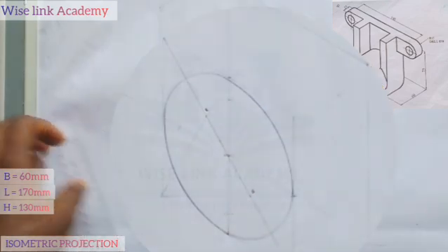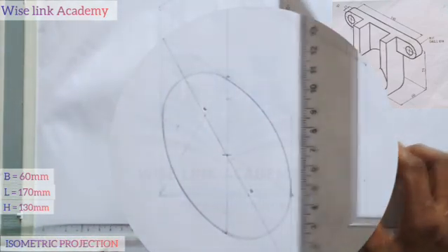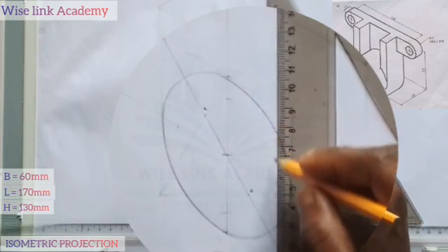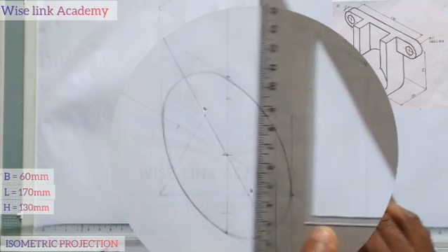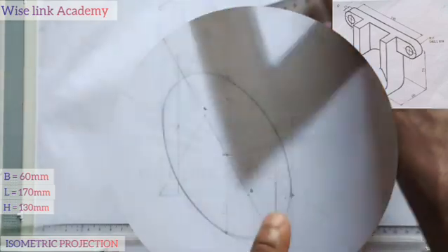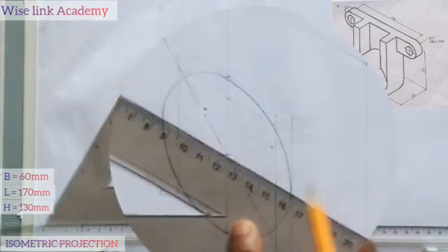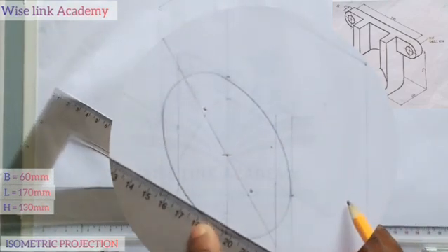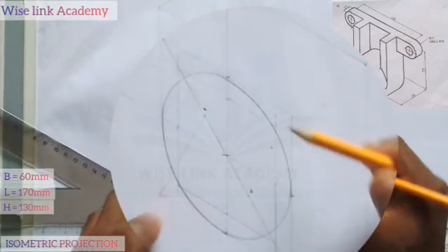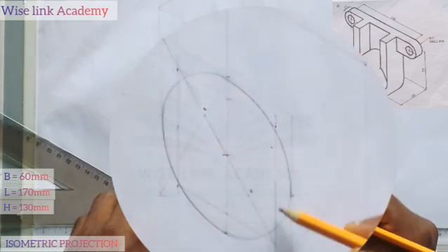I have this way. So I'll take my t-square. I'll take all those points and draw them down this way. Right, I'll just draw this point down this way. Also, I'll draw this point here down this way. Now I'll take my set square this way. I'll join those points together to produce a square, as I did initially. This point here, I'll join it down to this point. So this is what I want. This is a square I have produced. So you can see in front of you.